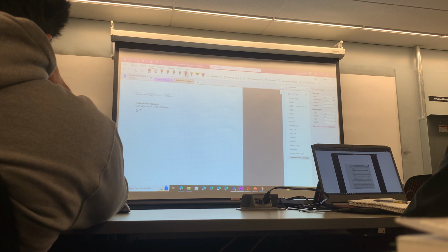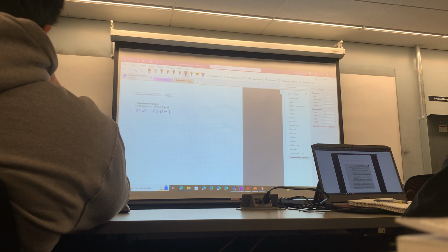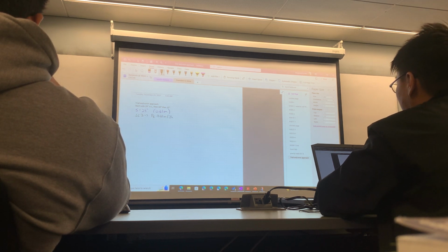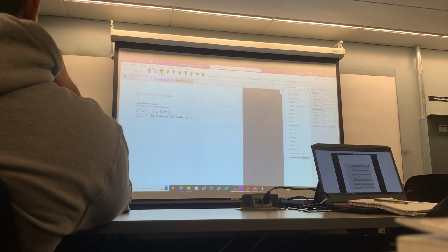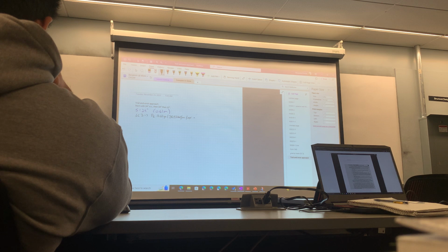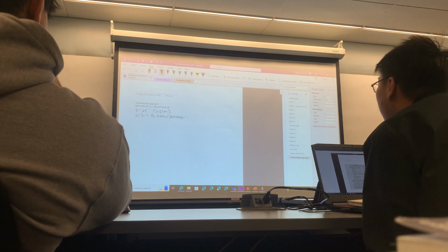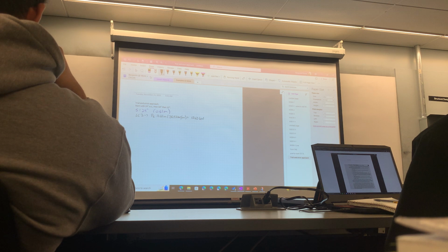So when S equals 24 inches, 0.61 meters, load case 3, PF is equal to 0.61 times 28.92 kilonewtons per meter width of wall. All right, so then you're left with, okay, and this is going to equal, just a second, 17.63 kilonewtons.